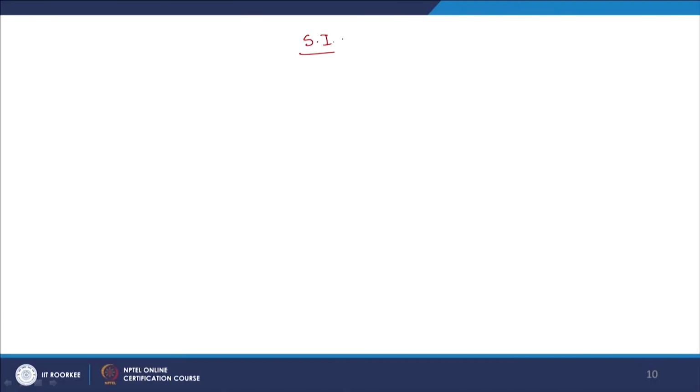This is equal to pH minus pHs, where pHs is that particular pH which would be in equilibrium with Ca2 plus for a given alkalinity, for CaCO3, when equilibrium is reached between CaCO3 and Ca2 plus. That pH is the pH at the saturation value, pHs, and the saturation index is calculated as pH minus pHs.